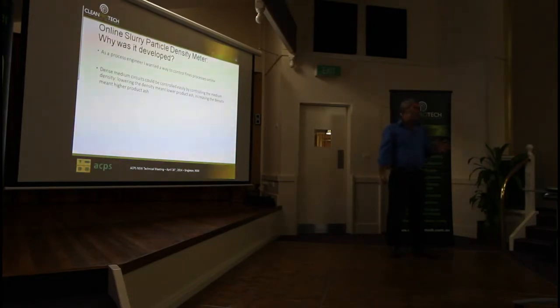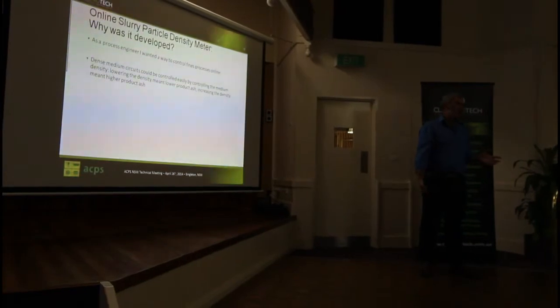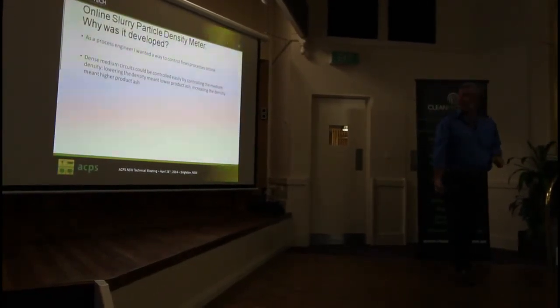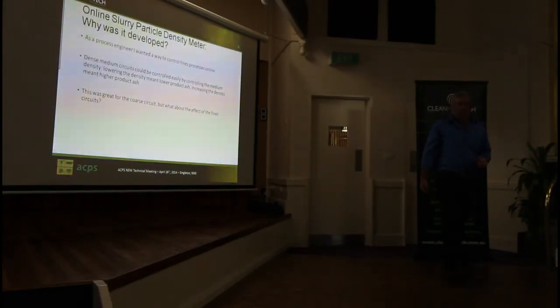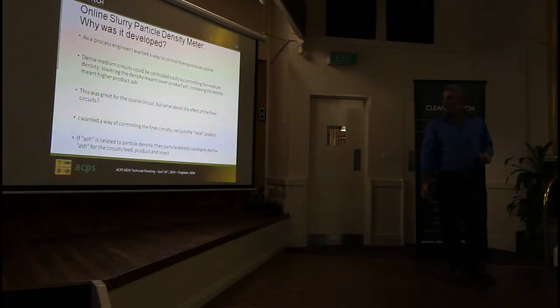Dense medium circuits, not a problem. We can control them by varying the medium density up and down as we need to. In fact, we're probably controlling the total ash in that situation. But what about the fine circuits? Okay, that was the thing I was really searching for: a means of controlling the fine circuits, not just the total ash.